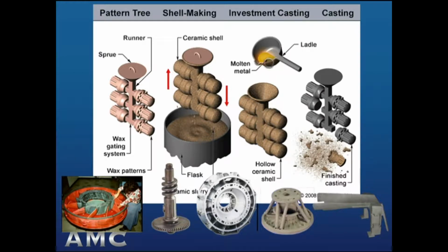So some of the examples of that process are the fan frame, a large titanium casting at the lower left with veins being wax welded into the pattern. There's a powertrain casting at the center left, which has all of the gear features, the worm gear, the spur gear, the hex to drive it, and so on, all as cast without machining.